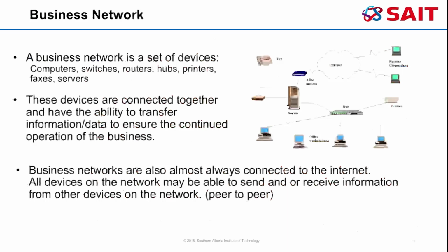Whereas an Ethernet switch within an industrial network, you would be looking at an industrial grade Ethernet switch, built to a higher standard, with higher approvals, more testing, military spec components, higher temperature ranges, vibration resistance, and all that sort of stuff, which of course pushes the price tag up, but supposedly it's built to a higher quality standard.